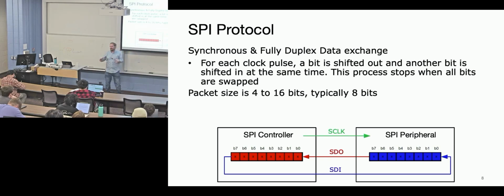ASCII is just a method for encoding alphanumeric information in binary. You might find for your projects that you like human readable things. You might not be so good at on-the-fly binary conversion in your head. It's fine, neither am I. So you could have two devices just talking back and forth in ASCII. ASCII is probably more relevant when you're talking about UART, because you're going to be sending stuff from your controller, probably up through your USB cable to your serial terminal. Yeah, the max ASCII value is 255.